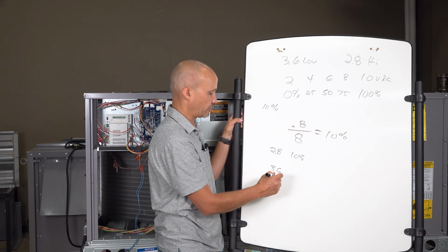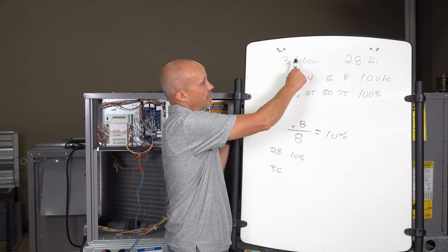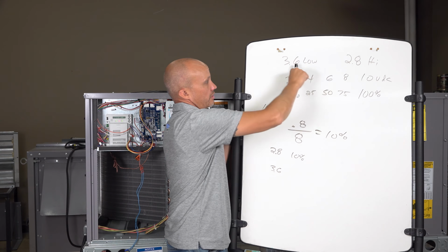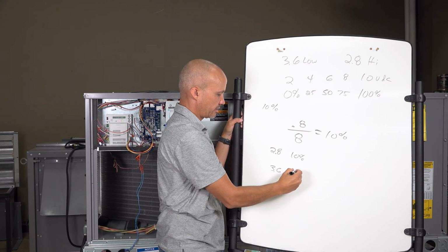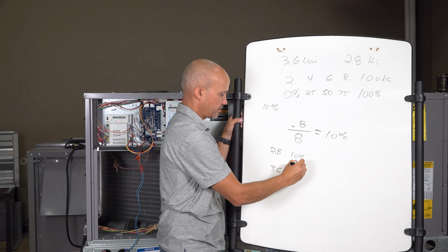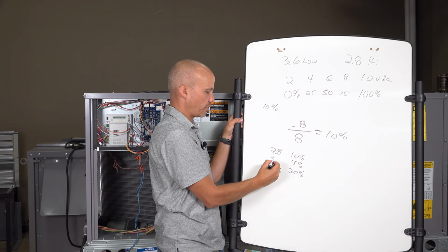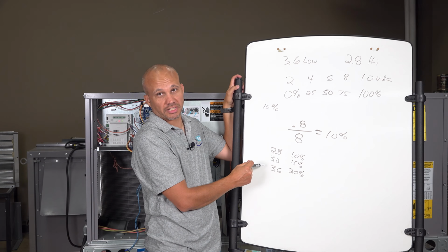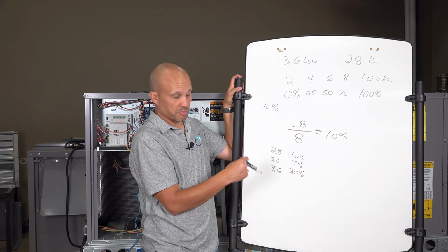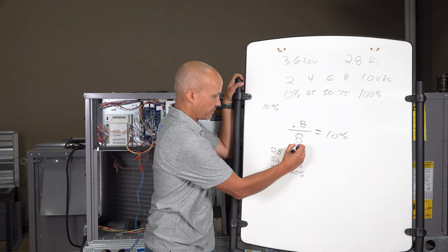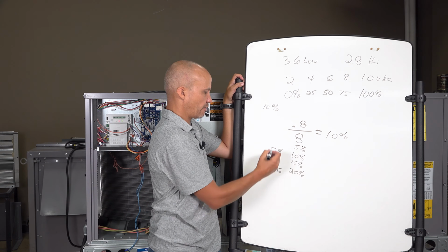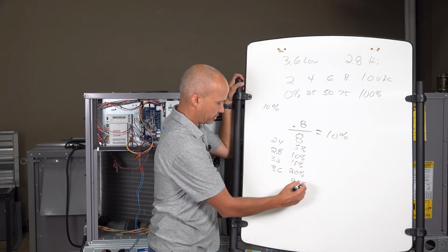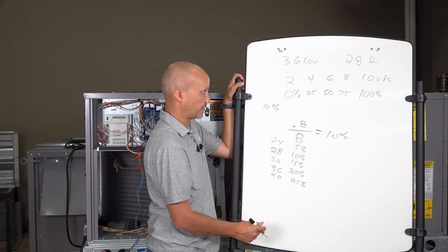3.6 volts, excuse me, is another 0.8 above that. Right? So 0.2 to get to 3, then 0.8, so that's 20%. If I wanted 15%, that would be 3.2 volts. So instead of doing this math all the time, you may want to just make a chart like this once and never think about the math again, because most of us aren't here for the math fun, right? So 5% would be 2.4 volts. 25% would be 4.0, like we said earlier.